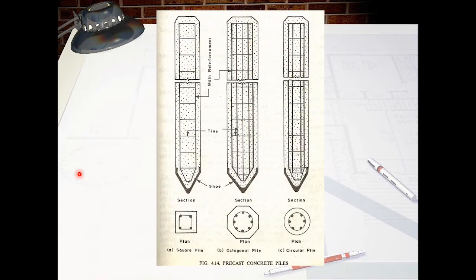The typical shape for precast concrete piles are square, octagonal or round in section. Generally, square section is commonly used. These are used on medium to large contracts where soft soil overlying a firm strata are encountered. Length up to 18 meter with section size ranging from 200 mm times 200 mm to 450 times 450 mm. So ini adalah size yang common for square pile.